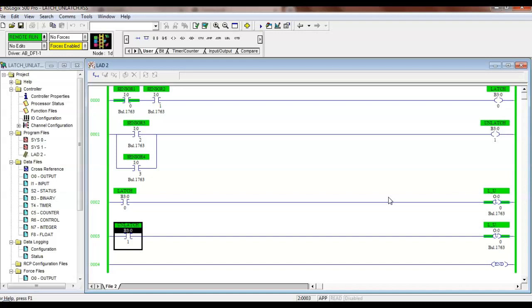So if I've got a coil that's in there to make a decision and it does not have to turn on the light, turn on the motor, turn on the solenoid, or communicate with the outside world, then I'm going to use an internal coil. In any PLC, the 1500s, the 314Cs, the CompactLogix, all of them support internal coils. These are coils that don't do anything to the outside world. They just make decisions until it finally goes to the outside.